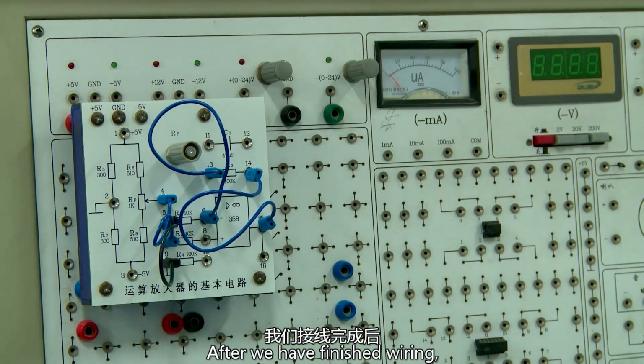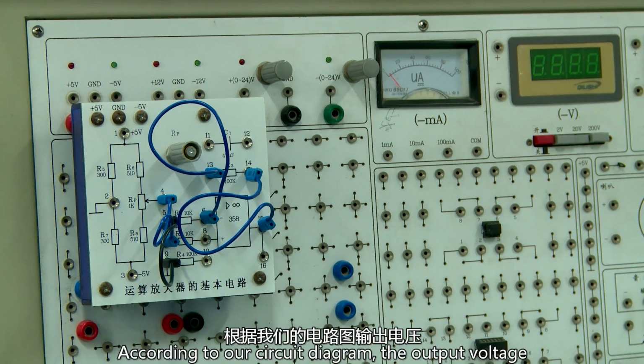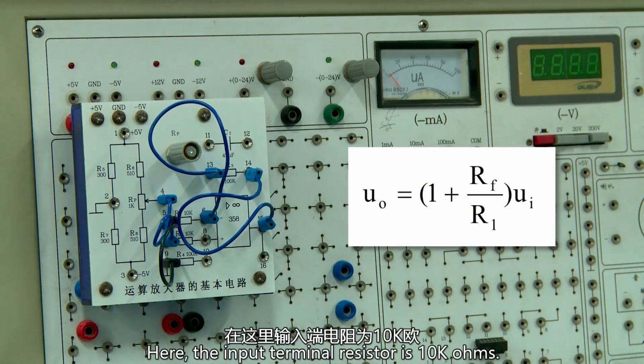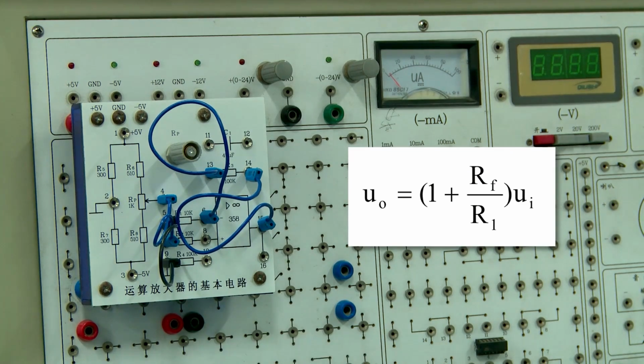After we have finished the wiring, how do we determine if the wiring is correct? According to our circuit diagram, the output voltage is given by this formula. Here, the input terminal resistor is 10 k-ohms. The feedback resistor is 100 k-ohms.